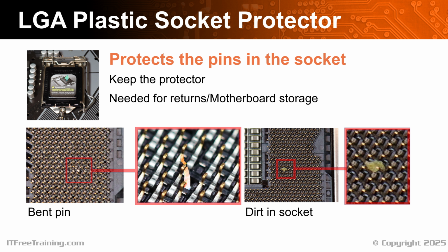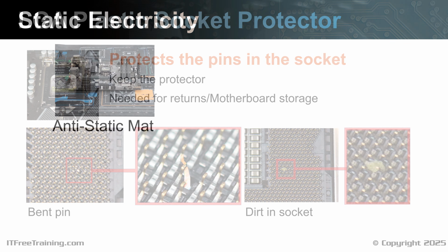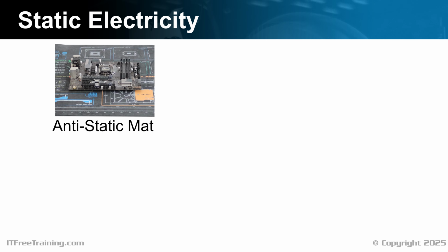Now let's look at how you can protect the CPU from damage. CPUs are vulnerable to electrostatic discharge. You should always use some precautions when handling them. This is a quick refresher, but we do have a whole video on this topic if you want to know more. If you have one, use an anti-static mat.